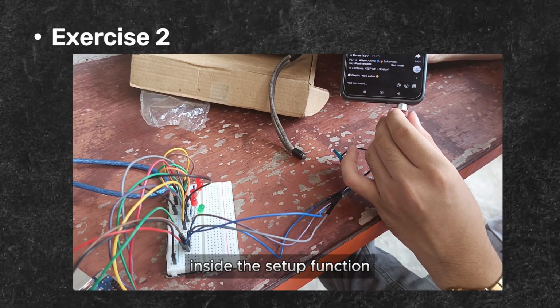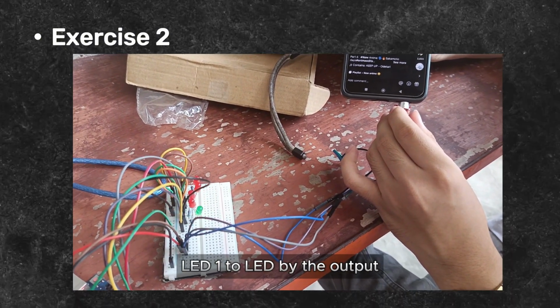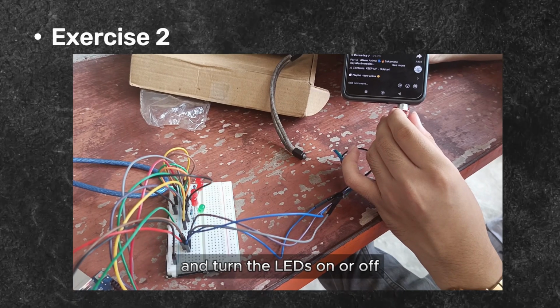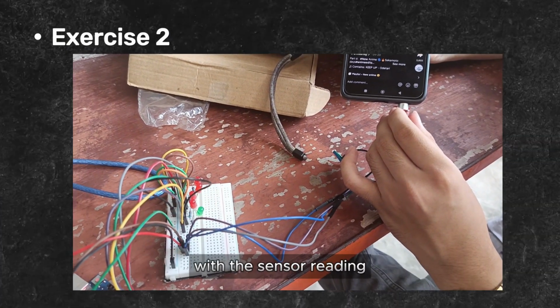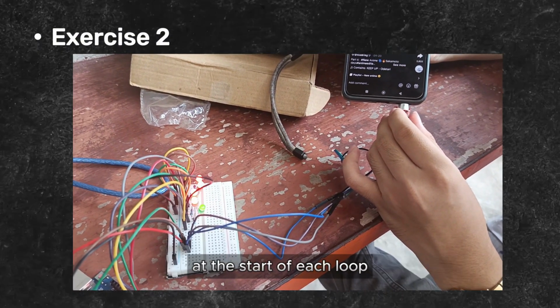Inside the setup function, we set the pin mode of all digital pins LED1 to LED5 to output, allowing the program to control the voltage and turn the LEDs on or off. In the loop function, we first assign the level variable with the sensor reading. Then, we set all the digital pins to low to reset the LEDs at the start of each loop.